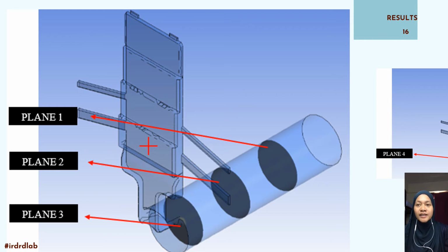Therefore, the short sleeve is divided into 3 parts, called plane 1, plane 2, and plane 3. The average pressure at the critical point will be calculated once the molten metal reaches plane 1, 2, and lastly plane 3. As pointed out, a high pressure is desired at the critical point to help the air pockets disperse and help reduce gas porosity. Moreover, another plane named plane 4 on the YZ axis is generated to help visualize the temperature contour and velocity streamline. The figure below portrays all the planes mentioned.